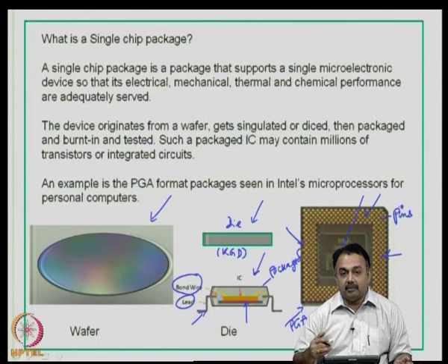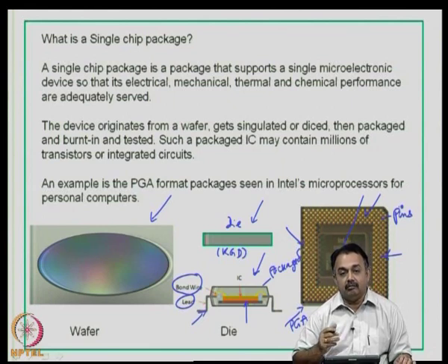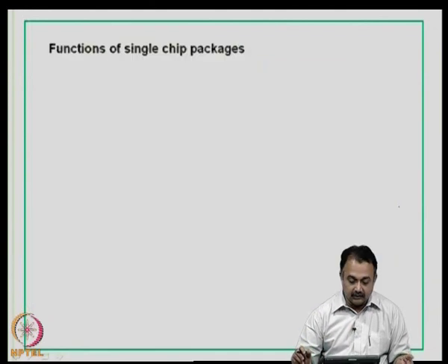I hope you remember what a pitch is, and then pitch is going to be a very crucial decisive factor in determining and custom building your format for the IC packages, because the industries are going to make it in millions. So, they have to consider cost, the materials, the number of IOs and the pitch to decide on what kind of package they can finally bring out for that particular design.